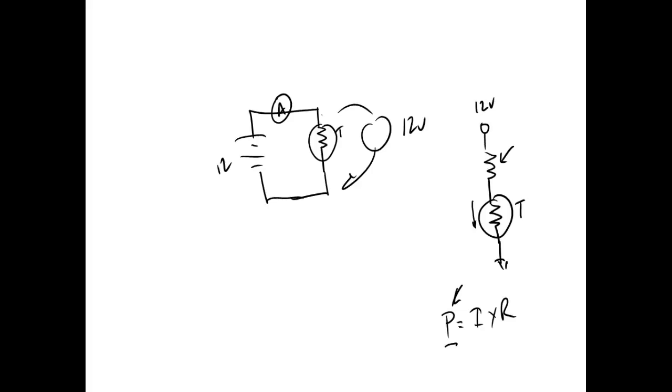But it makes sense. I've never seen a flow meter that works off thermistors, but undoubtedly it's out there because it's in the book. But you can see how that works. So what we'd have to do is we'd have to have two together, and then we have to compare them. Usually flow meters they'll put an impeller in here. So it's nothing but a propeller, and then they'll have a magnet on one side, and on the other side of the tube they'll have a Hall effect sensor, and it gets a pulse every time the blade flies around there.